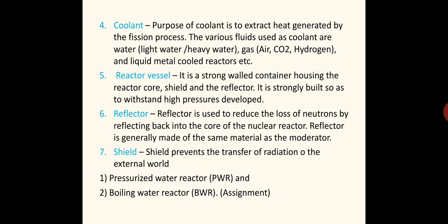Now coming to the next one, coolant. Coolant is situated inside the inner space, covering all the fuel rods, everything. Whatever heat is produced by the fission reaction is absorbed by the coolant, and through a particular duct it is carried to the outside of the reactor. Then it passes through the heat exchanger to give away the heat, and finally it is circulated back into the reactor. So the purpose of the coolant is to extract the heat generated by the fission process.